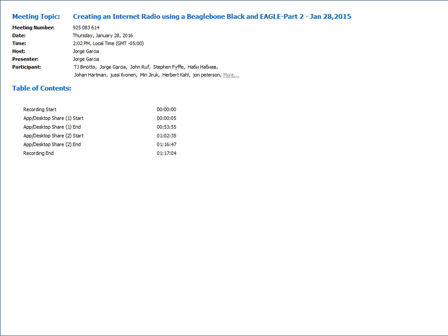So hopefully some of you could hear that. It's fuzzing out on me because I had read that you should always use an external cable for the Wi-Fi to separate it from the ground plane that's under the USB connector here. But I wanted to try it without it today, of all days, right? Normally I have it connected to a long USB cable, and that works perfectly fine.